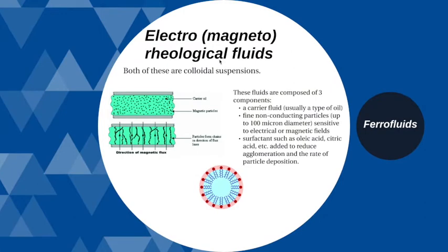And then the fluids, okay, this electromagnetorheological fluids, okay. This is colloidal suspensions. See here the magnetorheological fluids, okay. So you have the carrier, you have the magnetic particles, this black dot here, okay. When you give the magnetic flux or magnetic field here, it will arrange some structures here. It depends on the direction of the magnetic flux, okay, and it will arrange based on that magnet, okay.